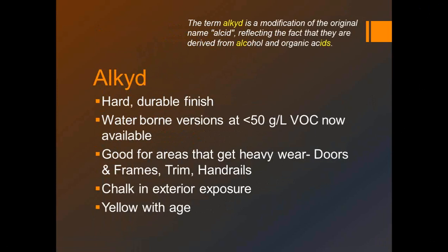And there again, this goes back to something that I'll say time and again, it depends, because there's more than one way to write a paint system depending upon what kind of protective value you want on that surface, and then what kind of maintenance aspect you want for that surface. We could help write specifications for 5-year repaint systems, 10-year repaint systems, and so on, depending upon what your owner wants to achieve in terms of maintenance.